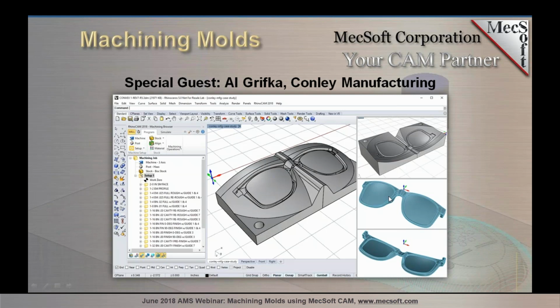So I designed this in Rhino, took the part positive, and did a split where I wanted my parting line. I did a couple different operations to make sure my parting line was right on the edge of the glass of the frame itself where I wanted it. And then we put some holes here for locating the two parts together. And as you can see, there are quite a few small cutters that will be going down in here.